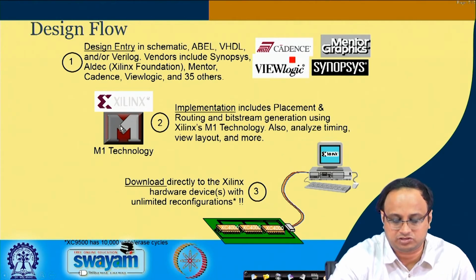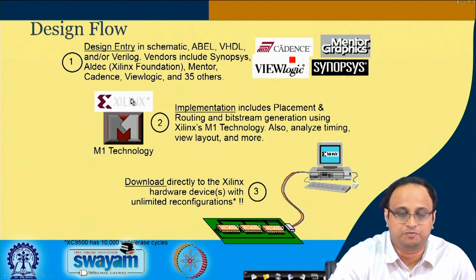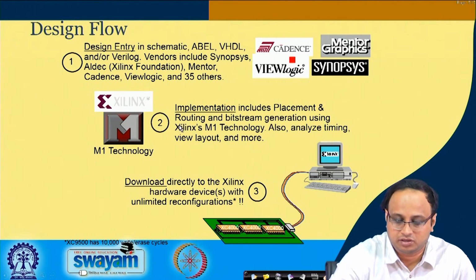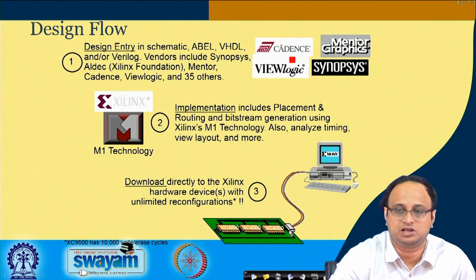so these are the FPGA tools which are used, but if you go into the ASIC world, then there are other tools designed by Cadence and Synopsys. The idea is that you basically do an implementation here. The implementation will include blocks like placement and routing, and finally the bit stream generation. And once the bit stream generation is done, you can download that bit stream through a port which is often the JTAG port, and you can configure the FPGA to work as you wish. Okay, so you basically can reconfigure the FPGA.